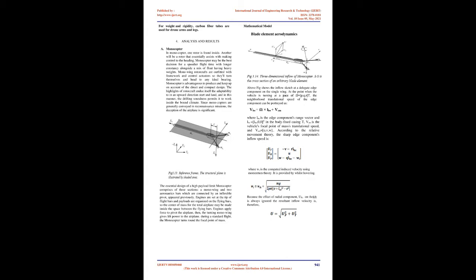3. 3D prints and CATIA designs. 3D printed parts. We 3D printed extra components so that we may have spares in the case of an accident, notably additional landing gears. Because most of the components serve two roles and are not flat on both sides, certain components will require support material to print. To conserve weight, we chose an infill of 20 to 30%, which produced excellent results.